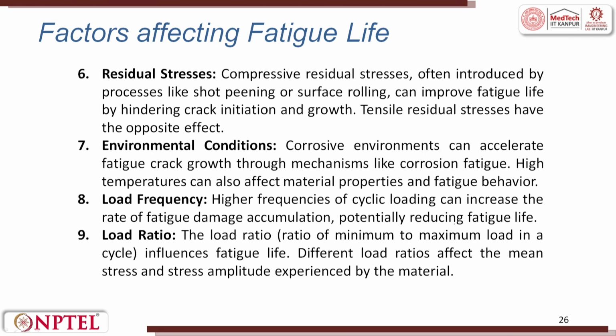The residual stresses which we have discussed in the previous lectures: compressive residual stresses, often introduced by processes like shot peening or surface rolling, can improve fatigue life by hindering crack initiation and growth. Environmental conditions like corrosion: see, if you have a crack, the water can go and sit inside, or an acid can go and sit inside, and the crack is very small. So, once this liquid goes inside, it can accelerate fatigue crack growth through mechanisms like corrosion fatigue.